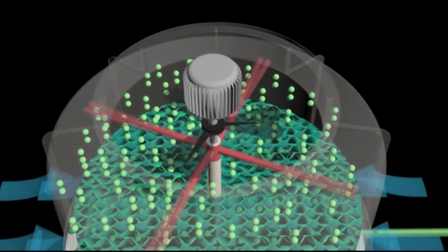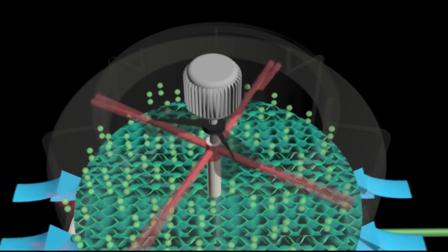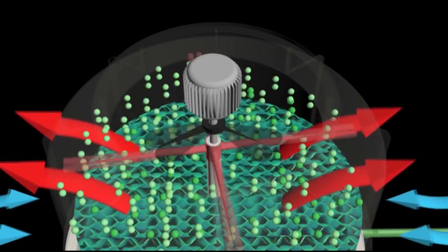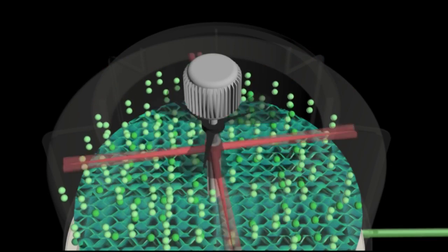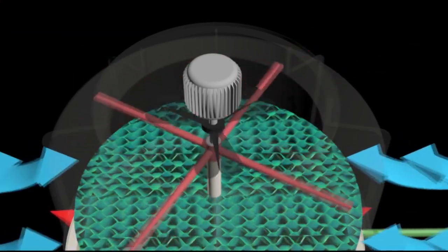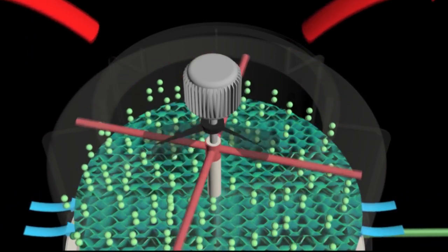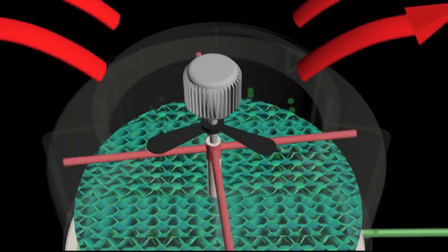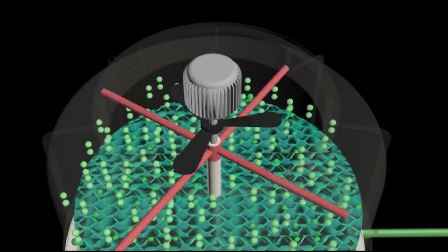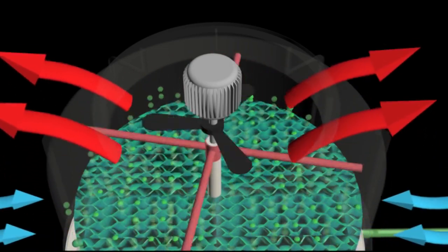Water will gush down through the fins to reduce the speed of water going down. This can delay the time and the heat can be absorbed more effectively by the surrounding air that passes through the fins. Air through the fins is forced by a rotating fan on the sprinkler blade rotated by the motor. This fan rotates with its gusts upward. This will cause the air to move from the bottom to the top of the cooling tower, which is opposite to the flow of the condenser water.